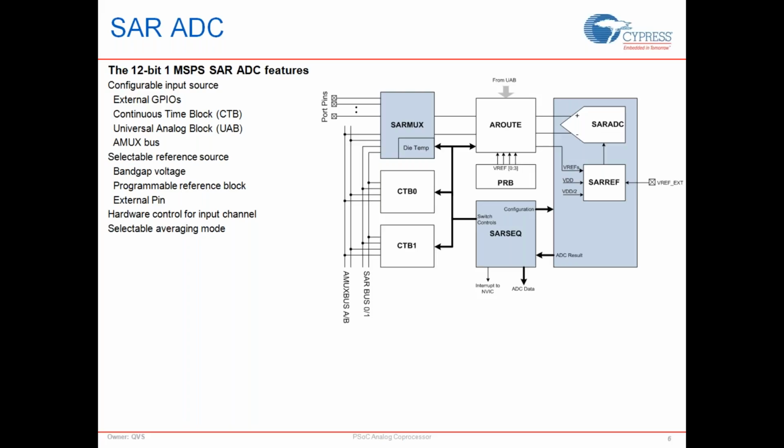You also have to remember this device has DMA inside it, so you can use your DMA to figure out what channels are done and pick those results from the result registers and move them to your buffers or something. So you don't necessarily need to use a CPU to switch channels or pick data out of the ADC for each of the channel measurements, or even pick data out of the result registers of the ADC and move it to a buffer. All that can be done using the ADC's hardware and a DMA combination.